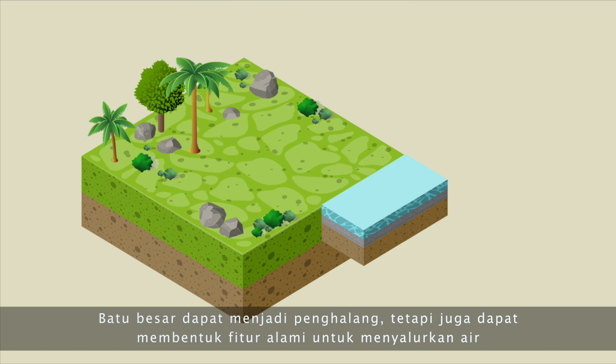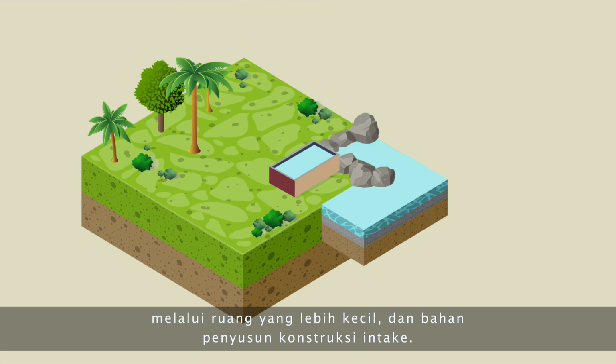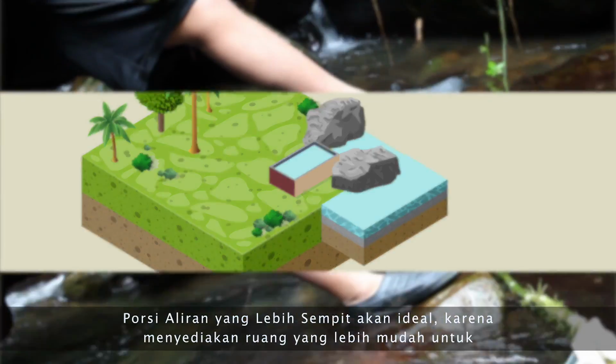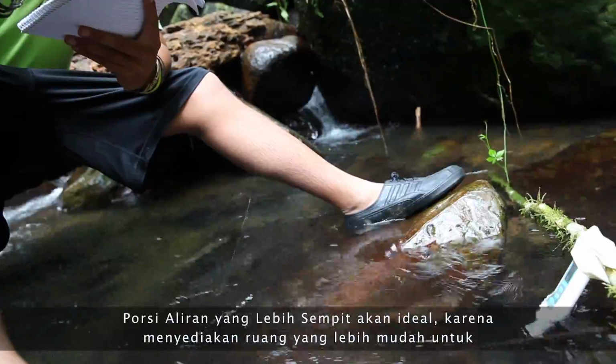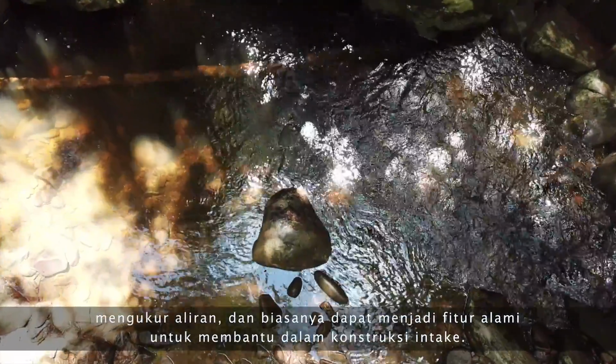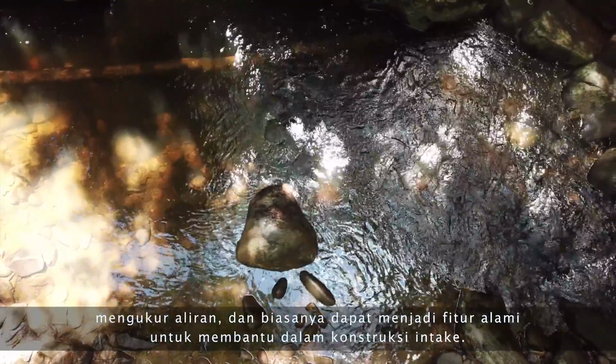Boulders can be obstructions, but they can also form natural features to channel water through a smaller space and the building blocks of intake construction. Rock walls may also be used to aid in intake construction, forming one or both sides of the eventual water catchment area. Narrower portions of streams would be ideal because they provide an easier space for measuring flow and can typically be natural features to help in intake construction as well.